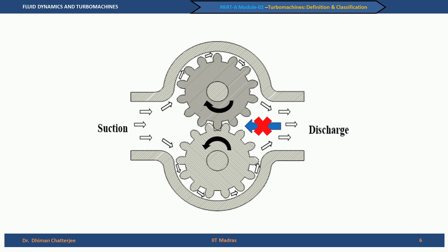In this case we see, first, there is no valve, unlike the reciprocating pump. However, there is a physical barrier to the leakage flow, and hence we can say that either a valve or a physical barrier is very important to prevent the leakage flow in the case of positive displacement machines.